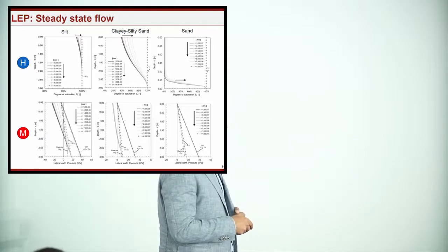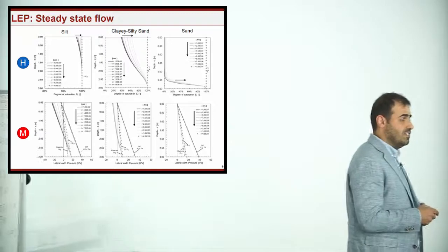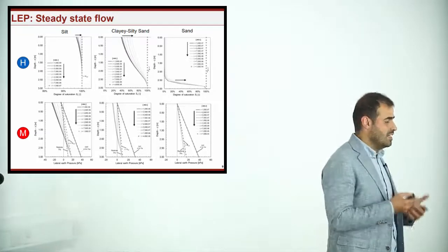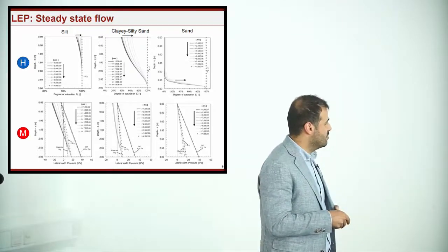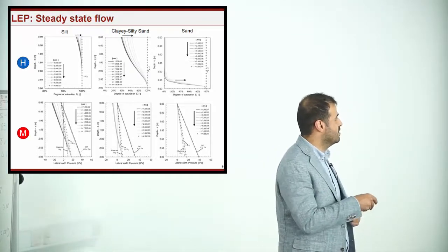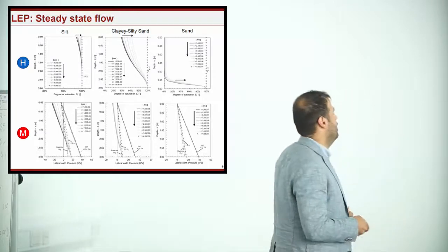Another thing I would like to highlight is that even if we consider the worst scenario, with the infiltration rate equal to the saturated hydraulic conductivity of the soil, the lateral pressure is almost half of that obtained by considering the soil totally saturated with the groundwater table at the top.